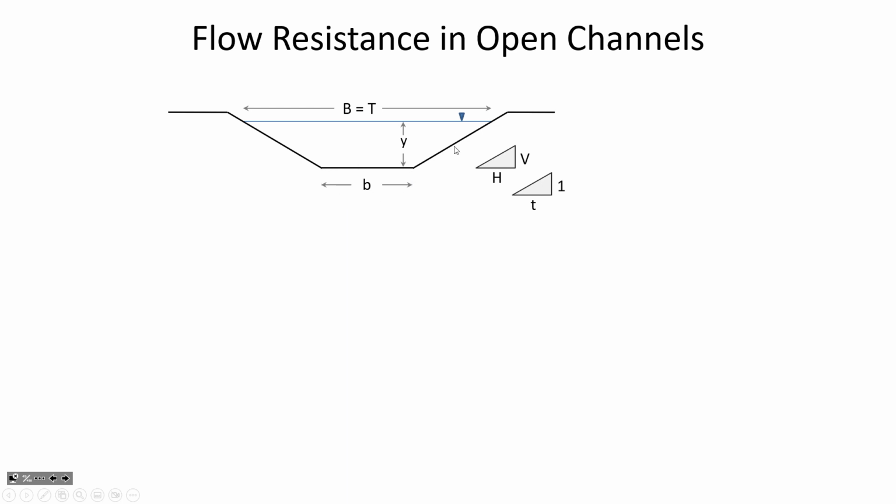And the reason why it's typical to have trapezoidal channel geometry is grass-lined channels or earth-lined channels couldn't have a vertical side slope. We can make a vertical side slope with concrete or rock, but other materials don't have the strength to hold up when water is flowing through a channel. Like a vertical sidewall like that would just collapse if it was soil. The shear stress that's being applied by the water as it's flowing would just eat away at it until it finds some stable equilibrium having to do with the angle of repose. But side slopes like this make it so you can have an earth-lined channel.